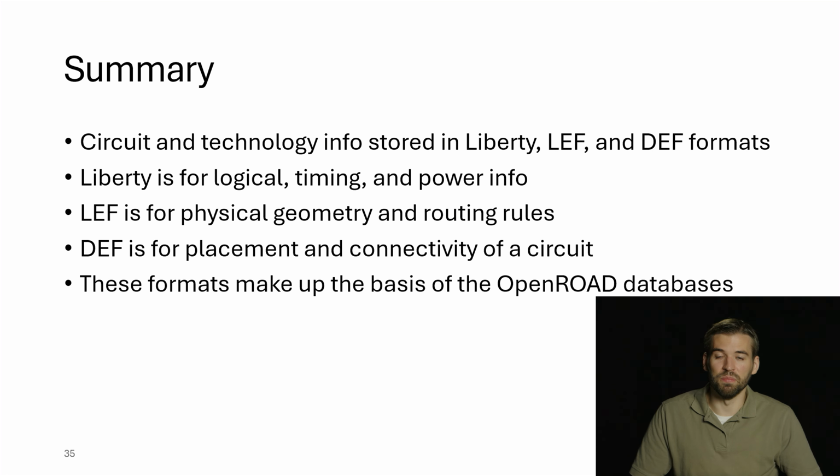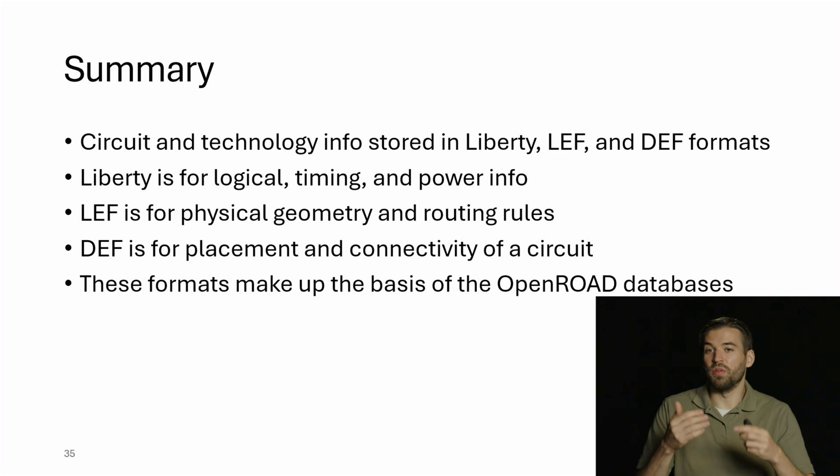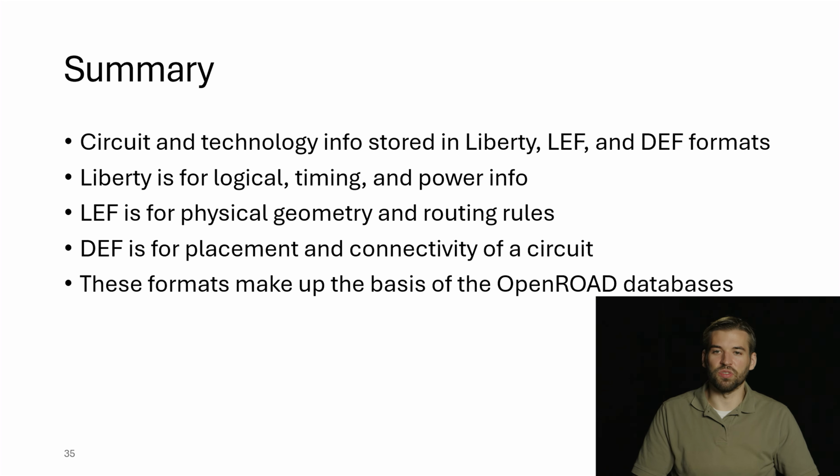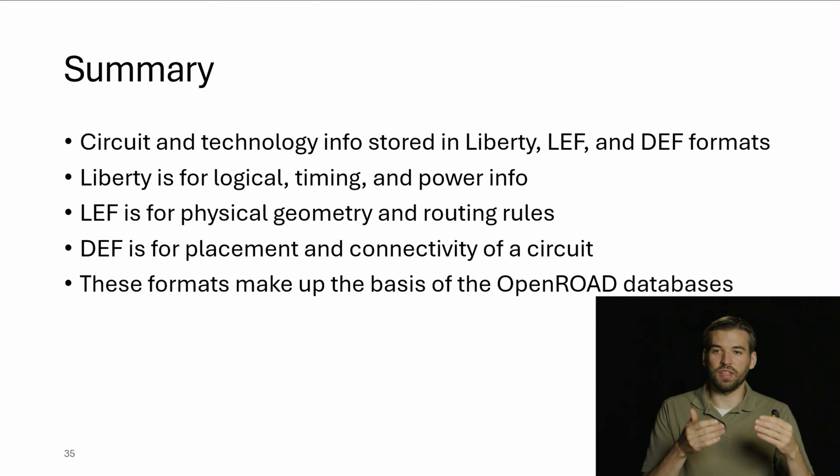So that wraps up most of the important information about what's stored in LEF, DEF, and Liberty. Do note that Liberty is going to be used for your logical, timing, and power information. And then LEF is going to be used for the physical geometry and routing rules for masters as well as the general technology of the process. And then DEF is going to be your design information. It's specifically for the placement and connectivity of a circuit.